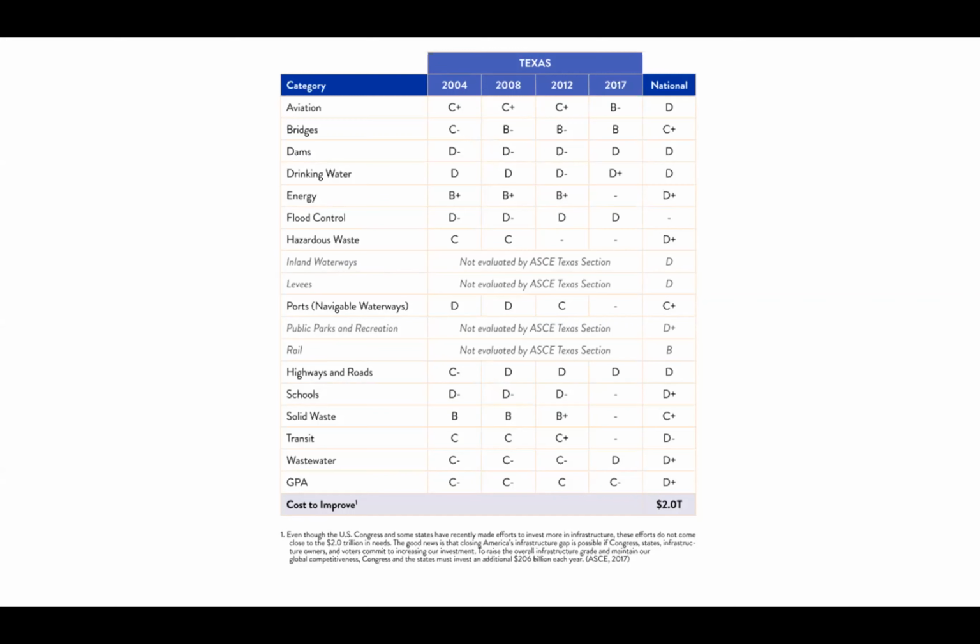The way that the procedure is right now is that the condition rating is still done on a 0 to 9 basis for deck, superstructure, and substructure. However, in the inspection process, the additional condition ratings, that is the 1 to 4 categories, are recorded. That is part of the inventory of the bridge now. So if a particular bridge has that issue where because one beam is bad, all beams are deemed bad, you do have that backup documentation showing which beam it is. That lets you go a little bit more granular with the decision making on what to do for that bridge, rather than just giving it a broad brush and saying the entire bridge is deficient.